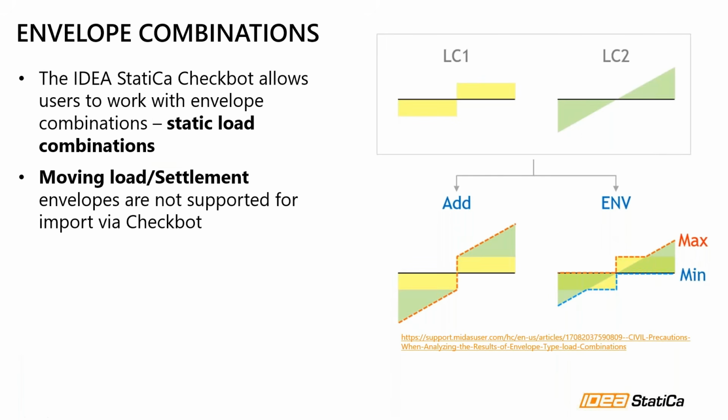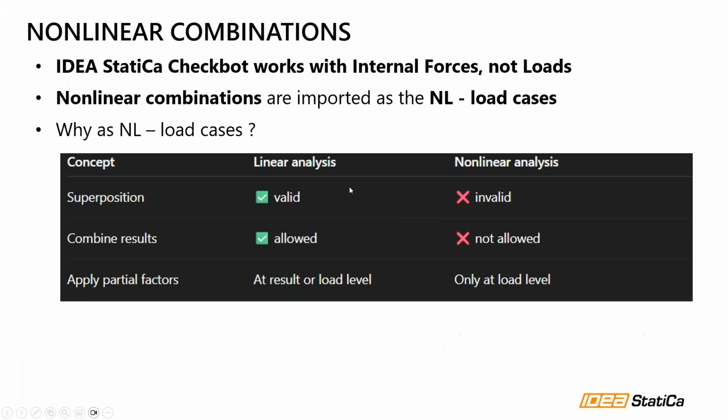And for those who are using a nonlinear analysis in their software, like a geometric nonlinear analysis to get some second order moments and additional internal forces due to the increment of the deflections or deformations, I have great news for you: we support the nonlinear combinations. But it is very essential to understand how we are translating the combinations into Checkbot.